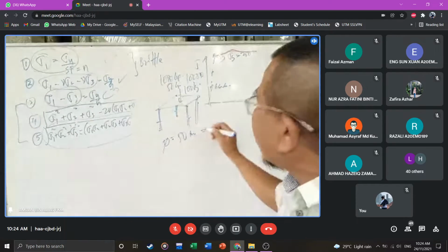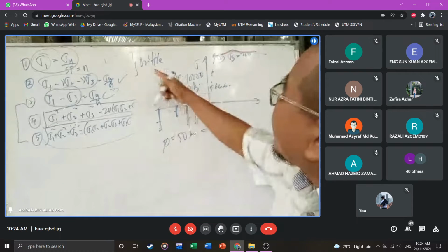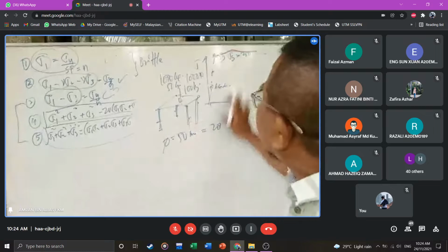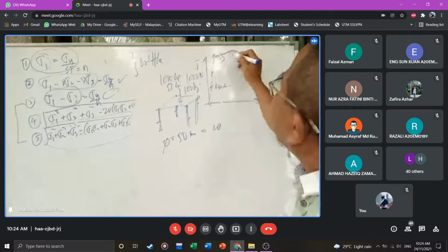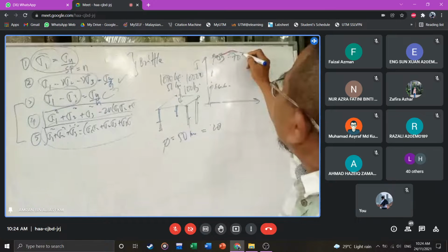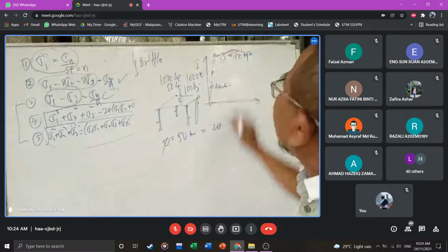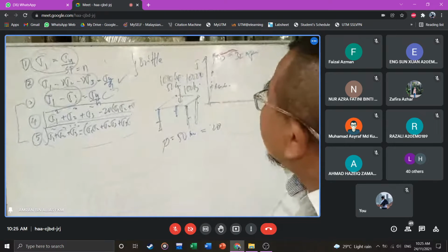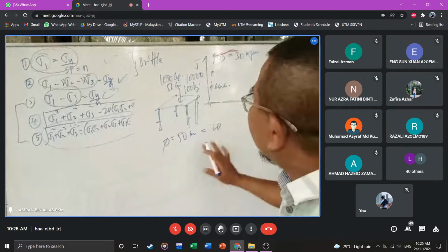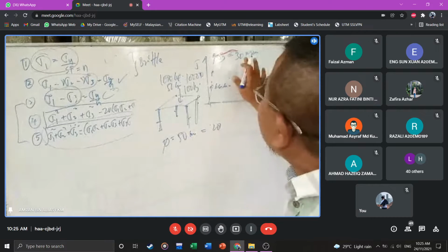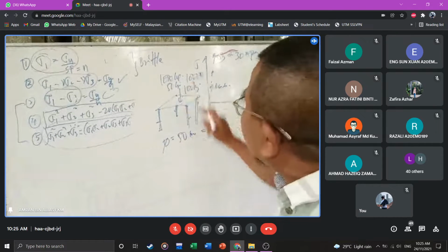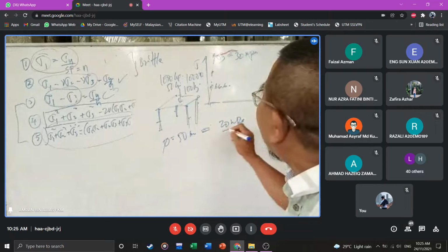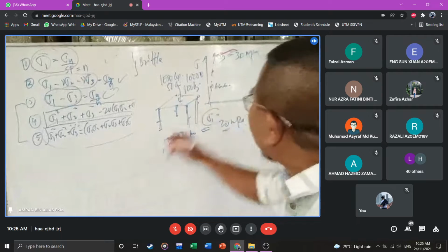And the stress is, divided by the area, exactly the stress is 20 megapascal. Let's say this is plastic. The sigma y for plastic, let's say 70 megapascal, or maybe the plastic is less, 30 megapascal. For that 20 megapascal there, you calculate it, divided by the size. Your sigma maximum is 20 megapascal.